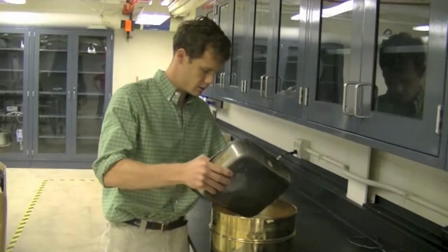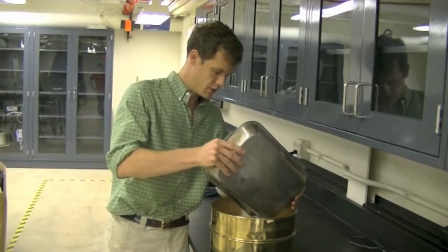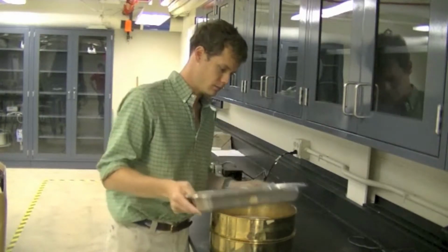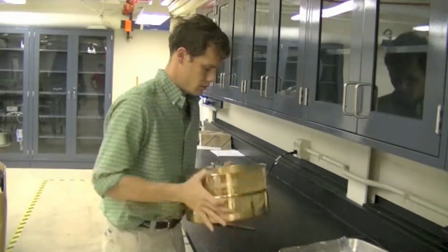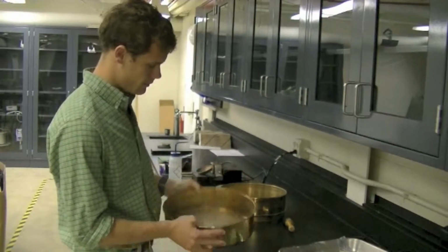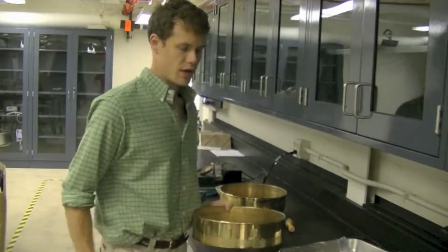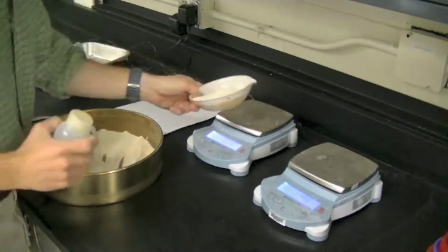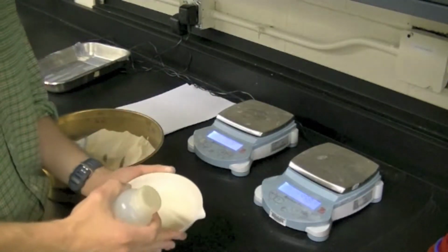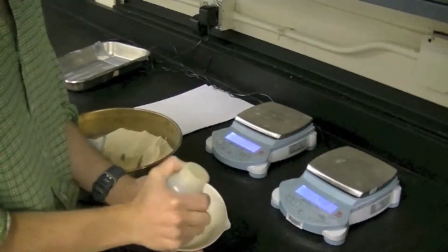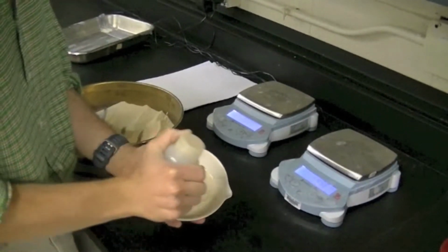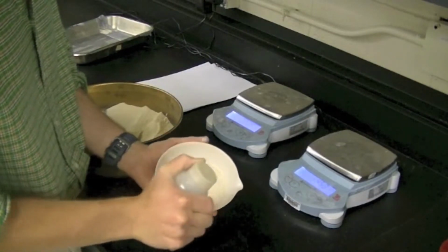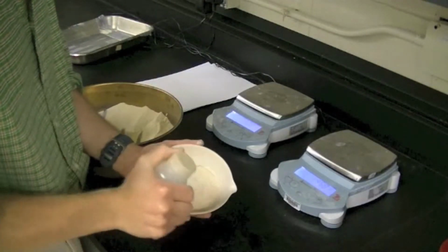In preparing for the Atterberg Limits test, we need to retrieve an air-dried or oven-dried sample and sieve it through the number 40 sieve. We must retain 150 to 200 grams that passes the number 40 sieve. Once the 150 gram to 200 gram sample is obtained, the sample is ready to be moisturized with de-aired water. Moisturize the sample slowly with a squirt bottle and mix with a spatula until the soil is consistent and thoroughly mixed. Moisturized material is about the consistency of peanut butter or thicker.